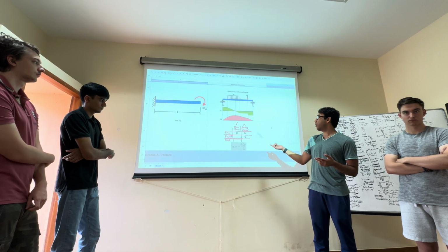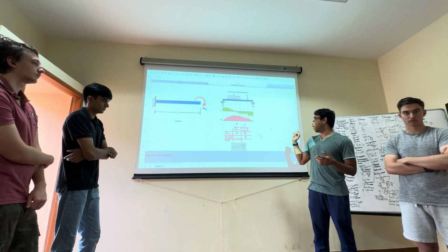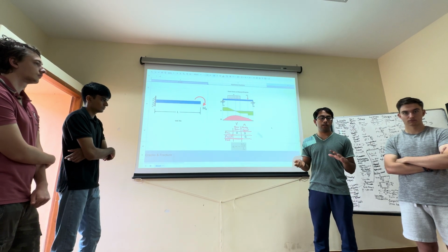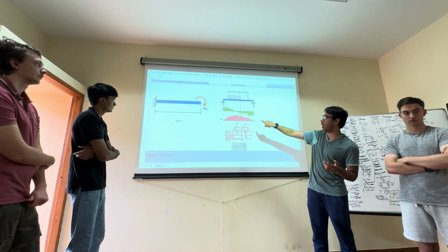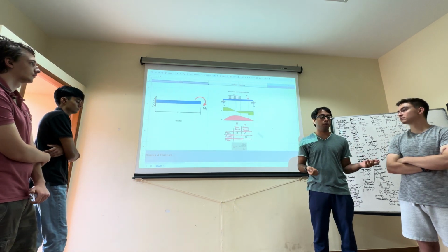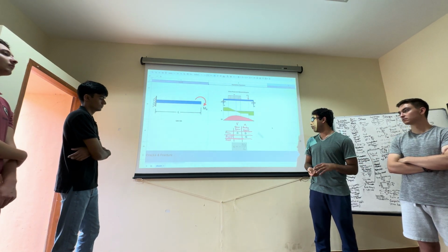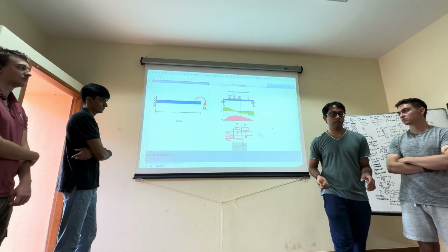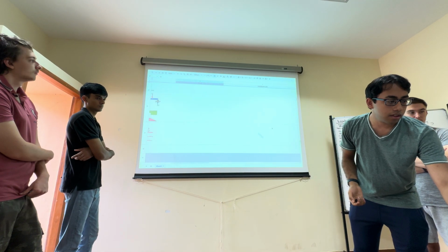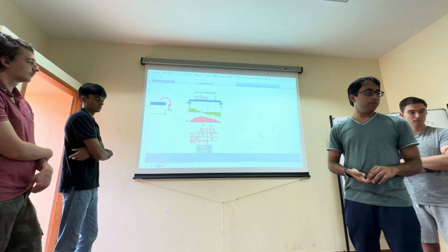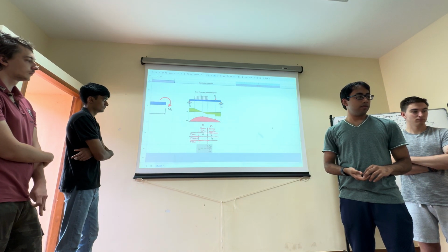And so first we have the shear force and bending moment examples, where if it's free like you see on the right end, it'll have a shear force of 0 and a bending moment of 0, as well as if it was pinned, it would have a bending moment of 0. If we go to the right, we'll see more examples. We can't generalize like that, because it also depends not only on the boundary condition but also the loading condition.